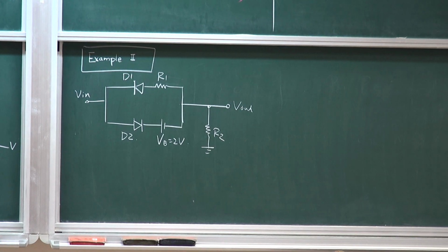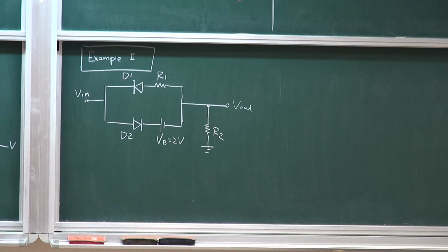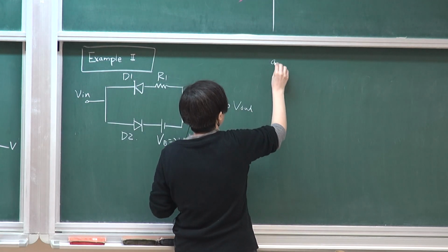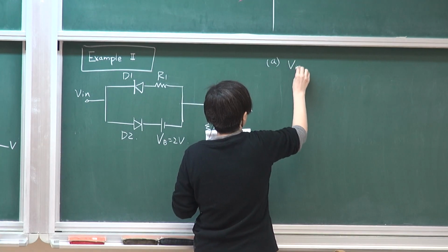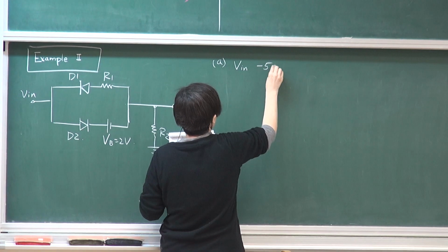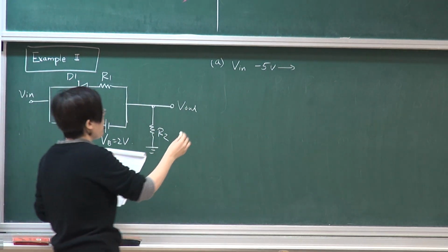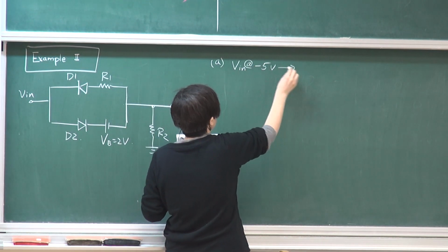How do you start? The starting point I find is mostly difficult for beginners. So the thing to do is that, of course, you start with the boundary. As we started here, we're assuming that it's starting at the most negative voltage, -5. So you start assuming that your Vin starts at -5, ramping forward. Okay, at -5, we're ramping toward 0.